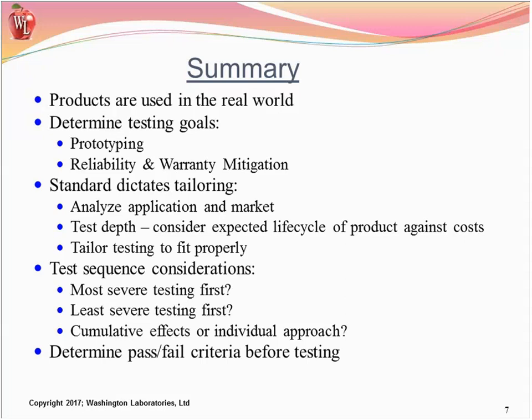How are drones inhibited from flying near protected airspace? Well, some of the models actually have a built-in failsafe in which it uses the GPS to know exactly where it is, and if it's within about a mile or so of the airport or protected airspace, it will not fly. But for the smaller models, like the toy store models, this is an issue because they don't have GPS systems and they can potentially fly near a protected airspace. So it really depends on the manufacturer and the quality of the drone, etc. Hope that helps.